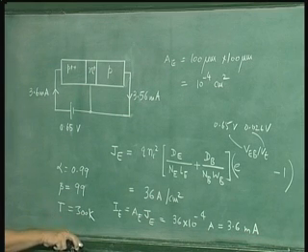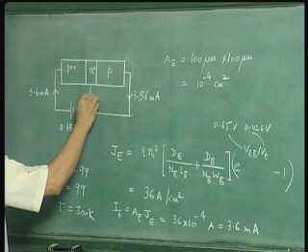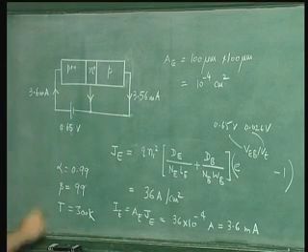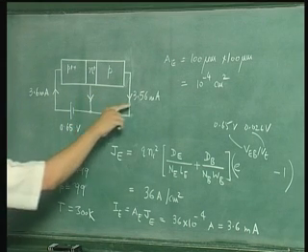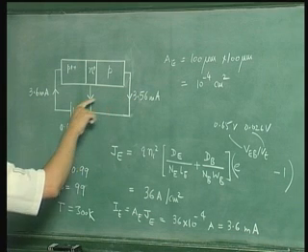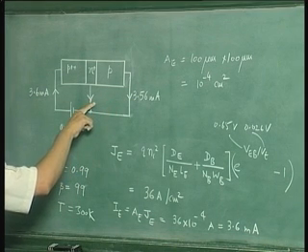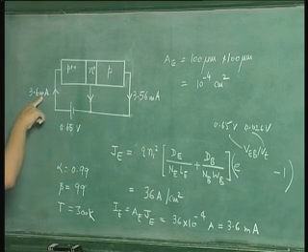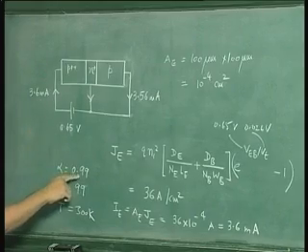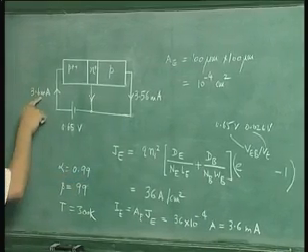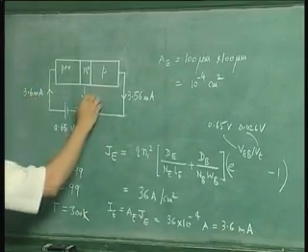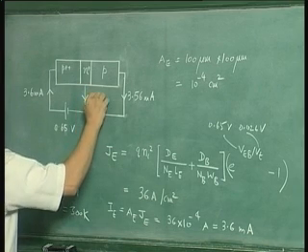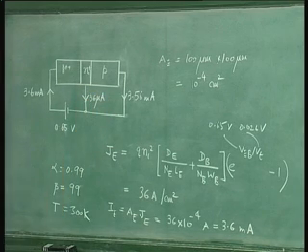And this base current IB would be beta times smaller than this, or it would be 1 minus alpha times this. So 1 minus alpha is 0.01, so 100 times less than this current. So this will be 36 microamperes. Those are the kind of currents flowing in the transistor for this biasing arrangement.